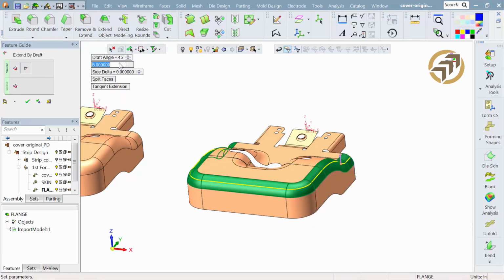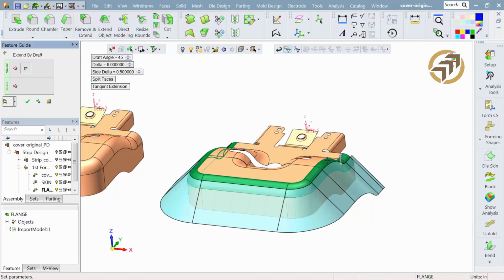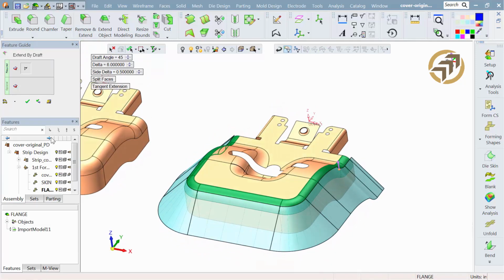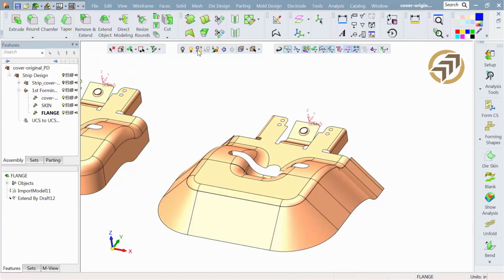It's got a good look to it as far as my angle, but I also want to extend the length out. I also want to make it a bit bigger, so I have plenty of distance to catch the flange. There you can see it's extended out off the end, so if there's any shape to that, it's got a face to land on. That's what we're calling a binder, or binder faces.